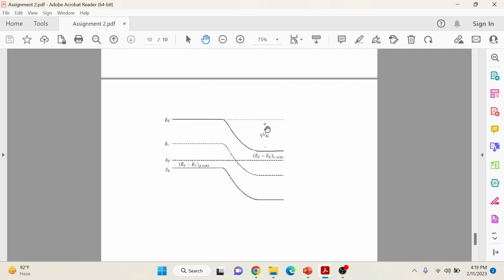The shifting occurs due to temperature, pressure, or some external stimuli, and we get more efficiency by playing with these factors. If we dope with more electrons, the Fermi level can shift towards the conduction band. If we change temperature or pressure, the Fermi level can shift towards the valence band.